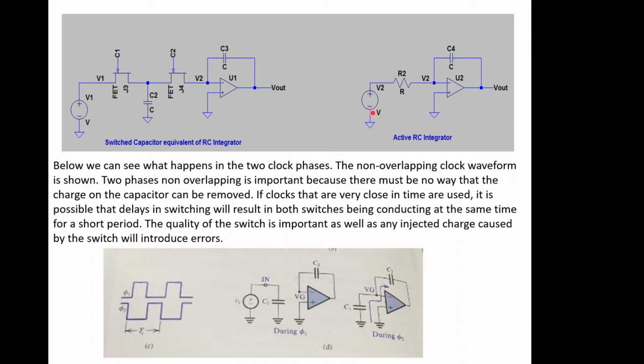So for example, here's what we will now recognize as an integrator circuit, which we're starting to realize are actually quite important in terms of filters and PWM and all that other kind of stuff. A switched equivalent of that is just this, where we replace the resistor with two switches and a capacitor, and then the time constant RC is going to be controlled by the frequency that we're driving this at here. So we can make a tunable filter, if you like, made of variable resistance.